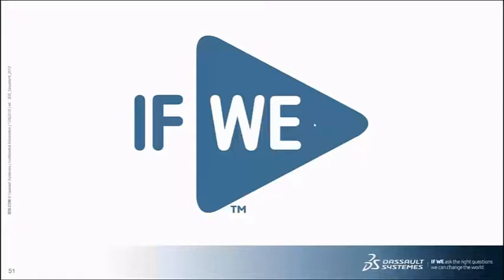I always thought that the slave should have more nodes. Why does the master need more nodes for contact? No, I'm not sure if I said that, but I shouldn't have. Or maybe it was in that picture, but the idea is that your slave surface would have the more refined mesh. So even in the sophisticated surface-to-surface algorithm, that is the recommendation.